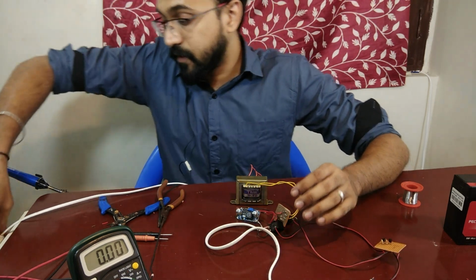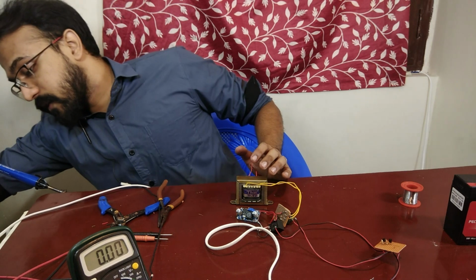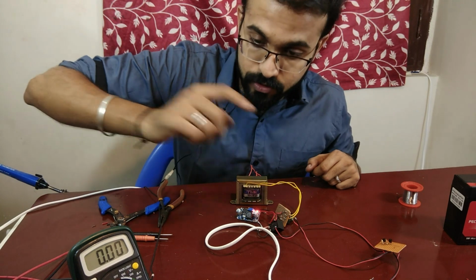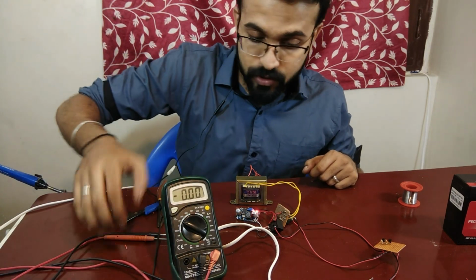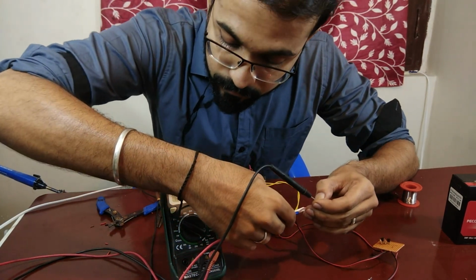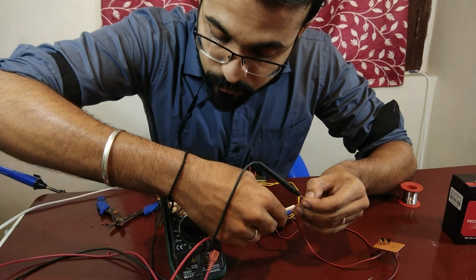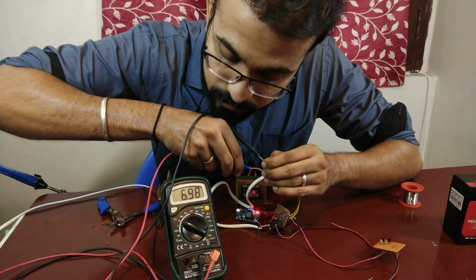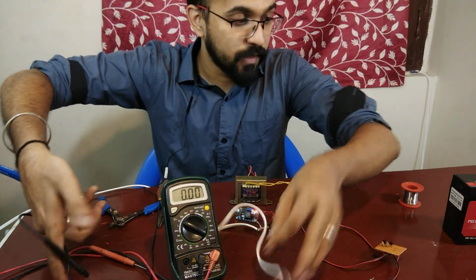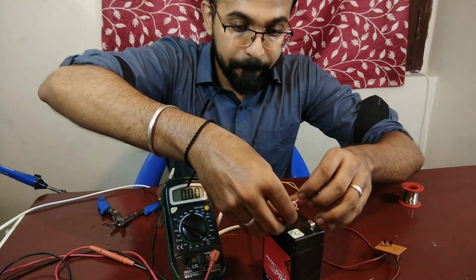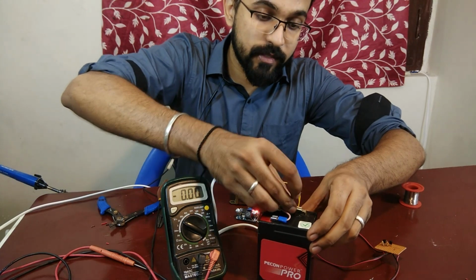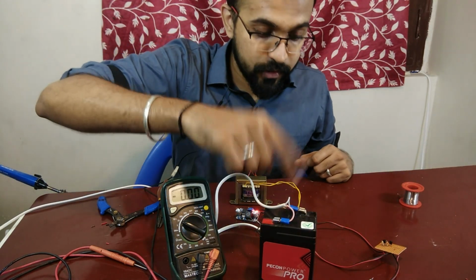So first we will connect the transformer, switch it on. So as you can see, the output here shows it's switched on. Now we'll set the voltage to approximately 7 volts. Okay, so almost approximately 7 volts, so I don't think I need to vary again. And now we'll connect the battery here. So I've already connected these clips to connect to the battery, and positive to positive, negative to negative.